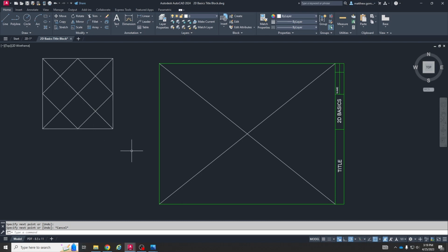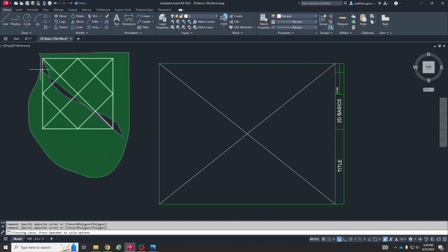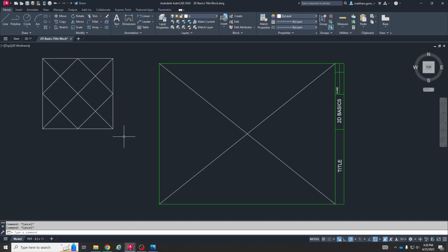And then I'm going to use the Move tool to move this point, basically that point right there, onto this point. And that should center my drawing. So again, I'm going to use the Move tool. I select my object. If you don't click and let go, what your mouse is going to do is it's going to look like this. A lot of people do this starting out. And it just makes it harder to select things. Like, yeah, it still accomplishes the same thing, but the easiest way to do it is just click and let go, move your mouse, click and let go.